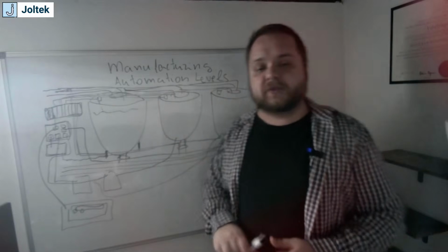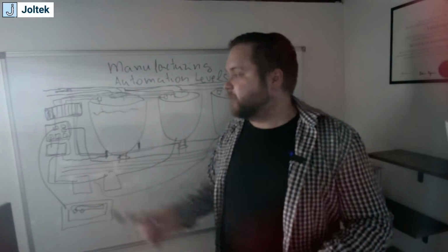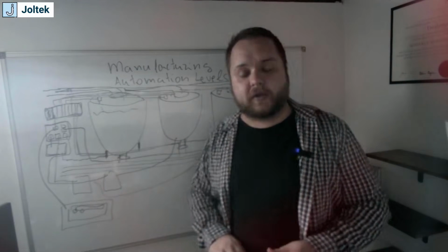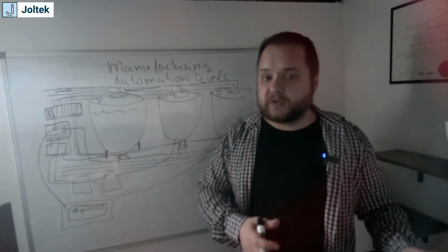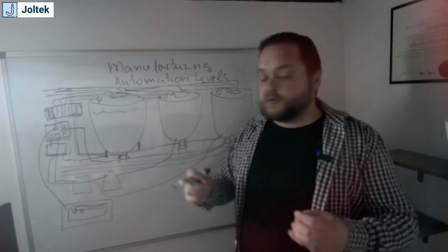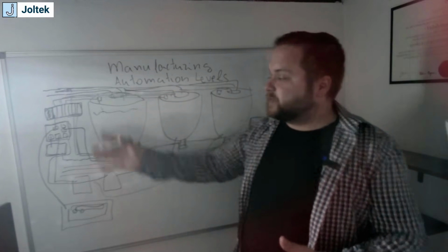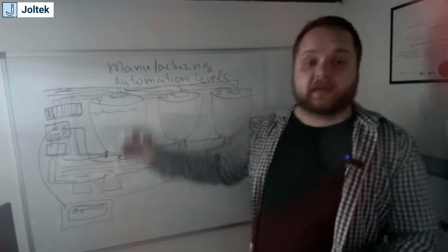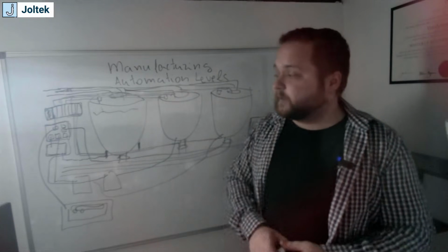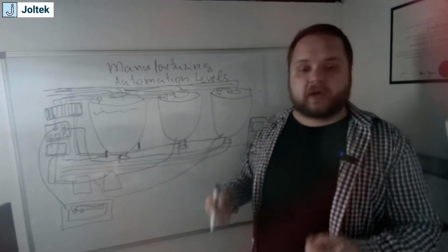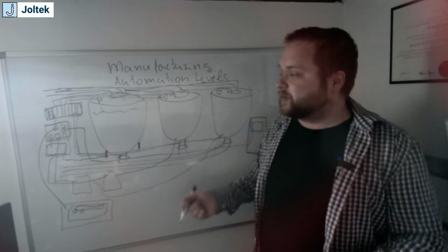So let's go back to the question of the switch, right? A lot of people will argue between managed versus unmanaged switches, right? Until you connect your plant, or at least until you connect a smaller area to the entire facility, the reasons for which we'll discuss a little bit later, I would argue that there's not a lot of value in having a managed switch.